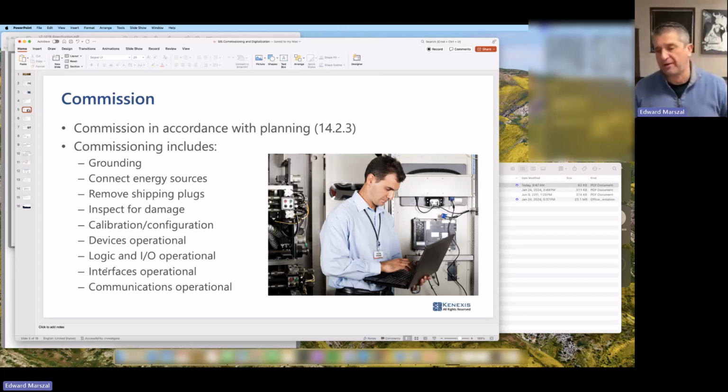They're using an operator interface, or maybe even one of many operator interfaces, because it's currently in vogue to have a dedicated operator interface for the SIS, along with that information being mimicked in the DCS operator interface. Of course, you might just have bells and switches and lights telling you what's going on. So you're going to want to chase that signal from the sensor all the way out to every last display device to make sure that the interfaces are working, the communications are working, everything's been properly configured to show the right signal at the right location.